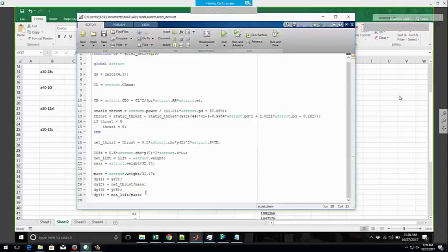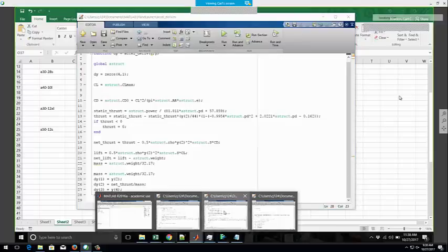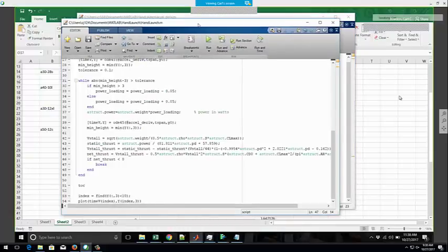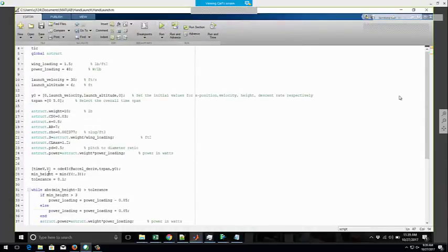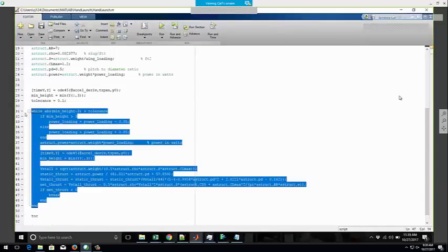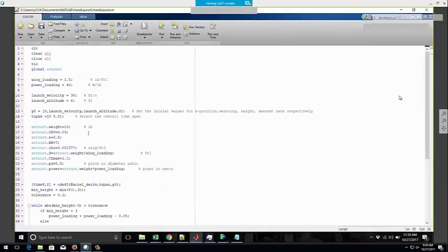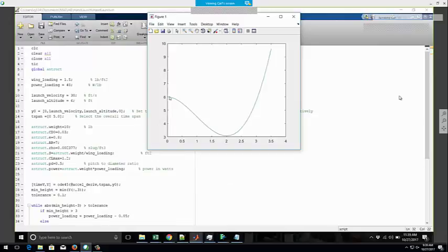So in this case, if we have a fairly weak throw, 20 feet per second, which is not unreasonable, and we have our wing loading here, if we pick this point, our wing loading is around 1.4 PSF, and then we're going to need something like 1.2 kilowatts, 1,200 watts of electrical input power in order to get a successful hand launch. Whereas if we get a smaller wing, that could go down to maybe down here. This is a very large wing at this point, but it's not impossible. It would go down to 700 watts.